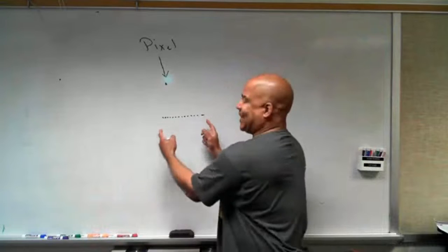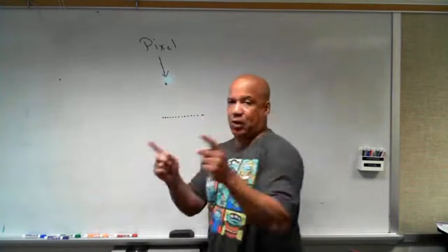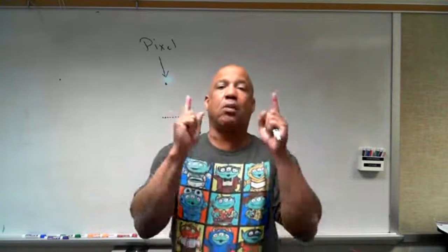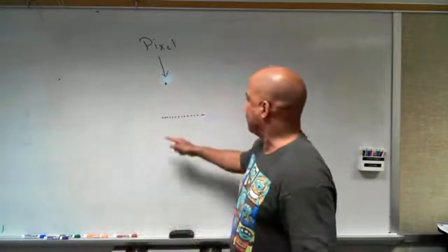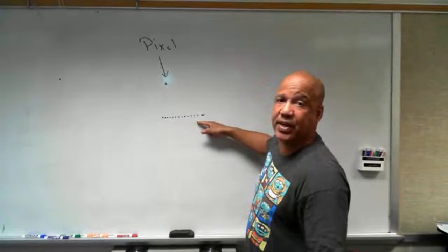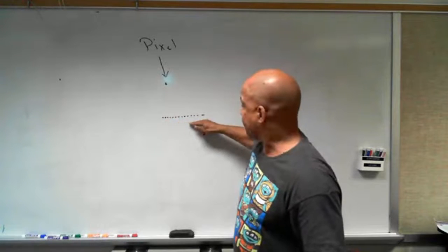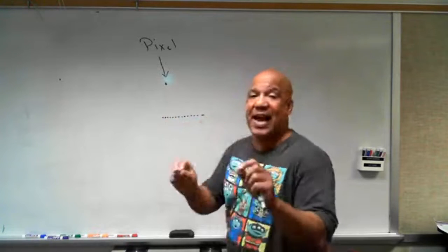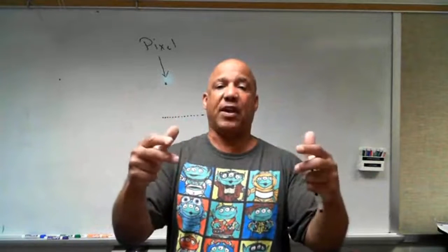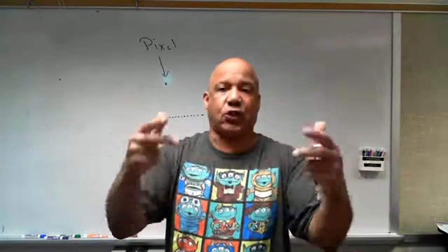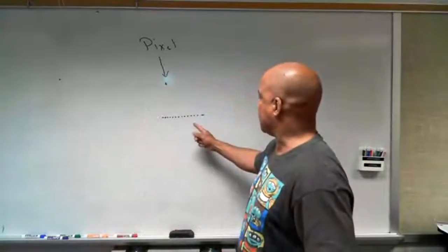We talk about the resolution. They look at how many of these little LED lights or how many of these little pixels, how many of those points you have in 1 inch. The more pixels per inch you have, the higher the resolution. So if I use, instead of maybe I have 25 lines here, 25 dots here, if I use 50 dots to represent each point here, then the line's going to look a lot crisper. The picture I make or compose with that line using 50 pixels per inch, it's going to look a lot sharper, a lot cleaner than if I'm using 25.